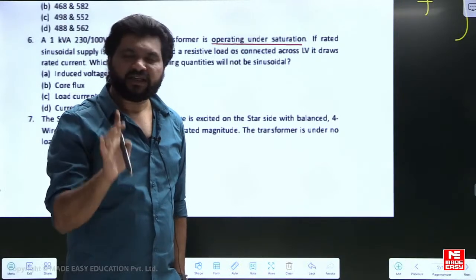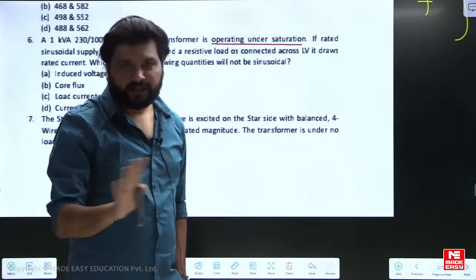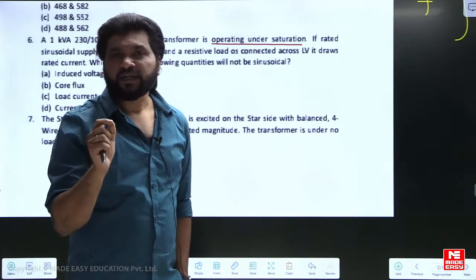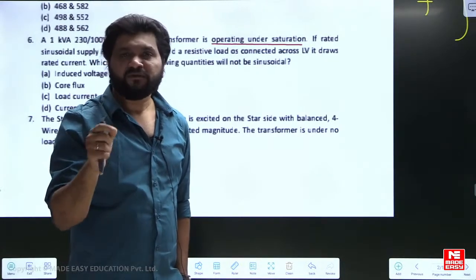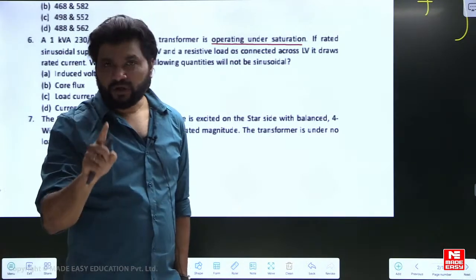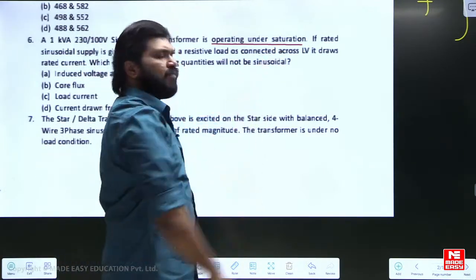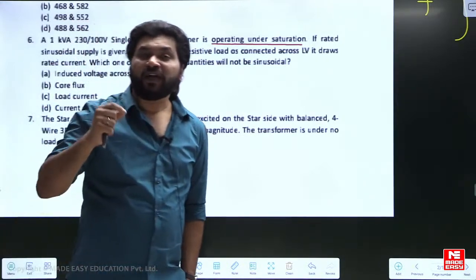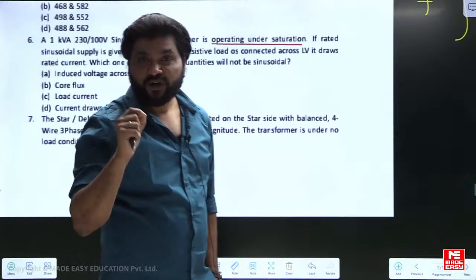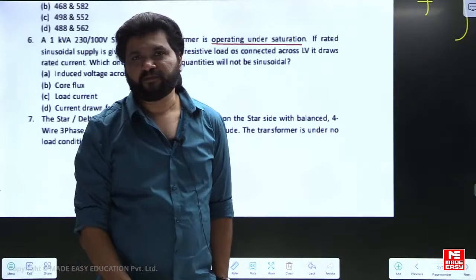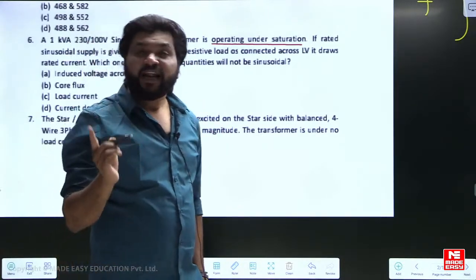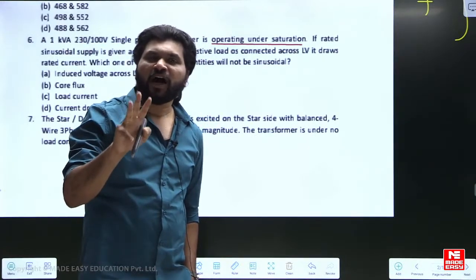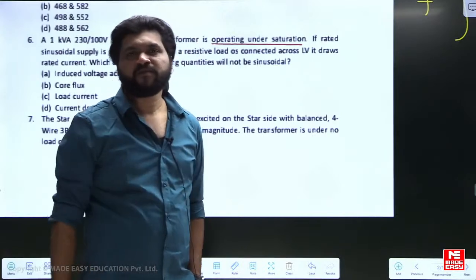will draw a sinusoidal current naturally. This current, which is sinusoidal, doesn't make sinusoidal flux in the core because the core is saturated, due to which flux establishment in the core will be flat topped. Then this flat topped flux contains a dominating third harmonic component in it.